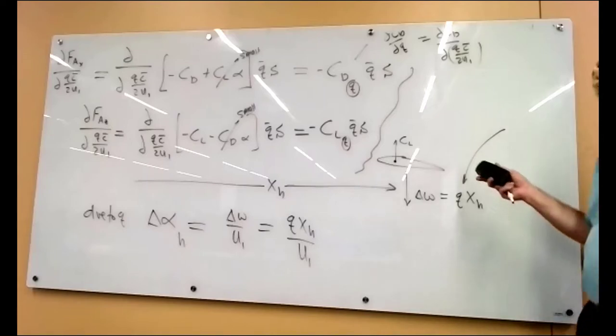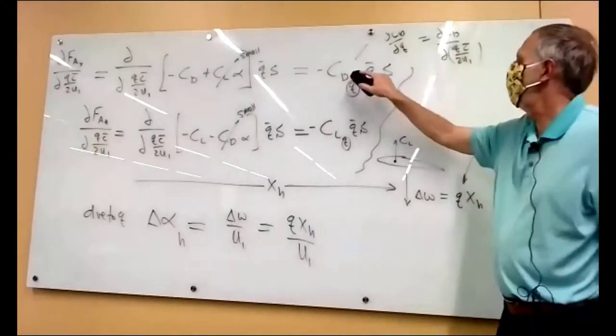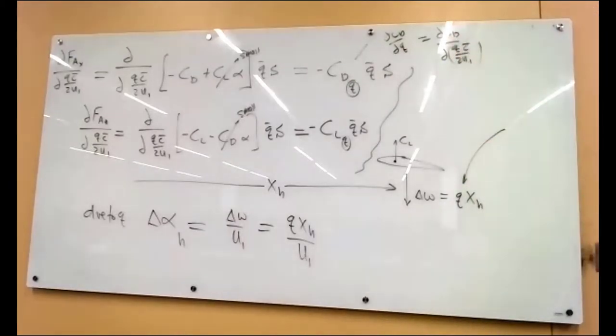And it turns out if you forget this, and let's say you take this and you just multiply by Q in the formula, you get a way bigger effect than it really should be, because here you're dividing by U1, which is a big number. We actually, a long time ago, developed a MATLAB model for an airplane and forgot to do that, and we were getting crazy high forces, and it's because of that. We forgot to do Q times C bar over 2U1.